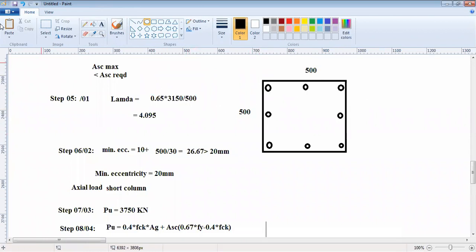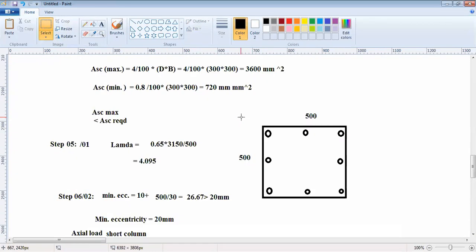It's very easy then, because on all faces you have equal distribution of the bars. It's better to provide bars in such a fashion. Now all of these longitudinal bars are each 20 mm in diameter, and you have stirrups around these. Oh, sorry, the rings around these, the transverse bars around these. So how do we provide that?